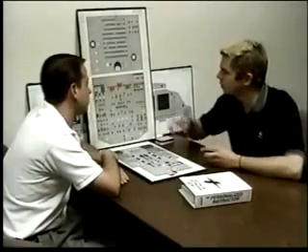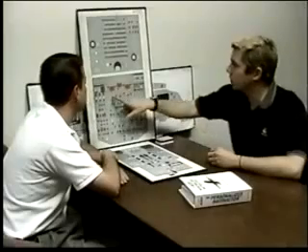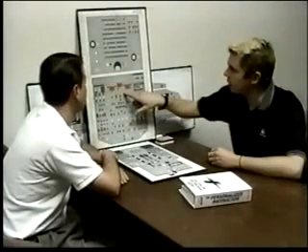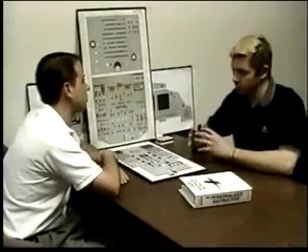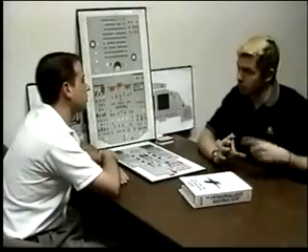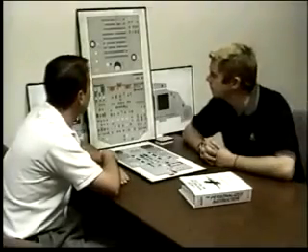No, there's 2 reversible motor pumps that are on here, and the yellow, for instance, let's say we have a low green system pressure. The yellow system will drive that motor pump, it'll drive a shaft to the other motor pump, and it will then pressurize the green system. So there's never any exchange of fluid.